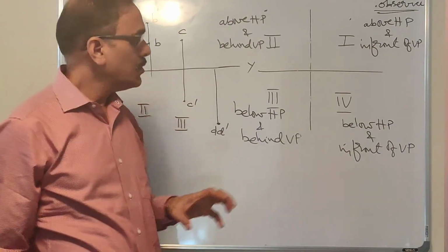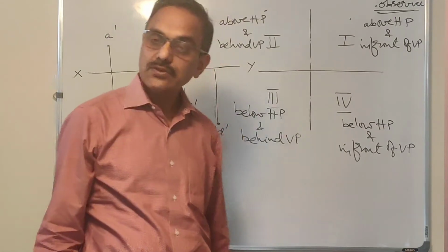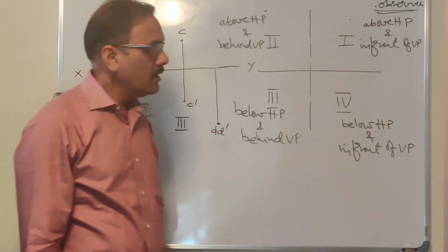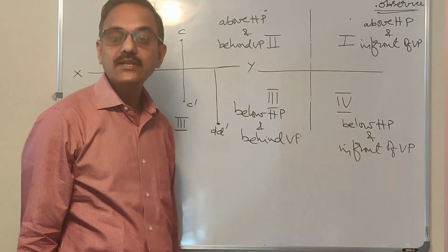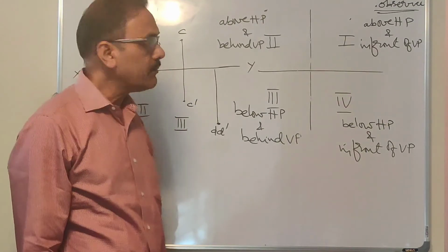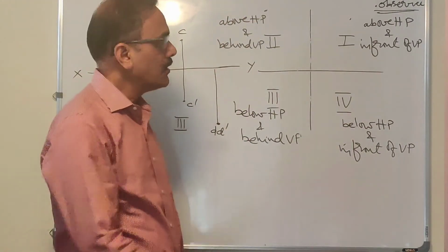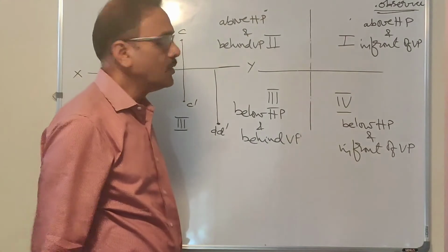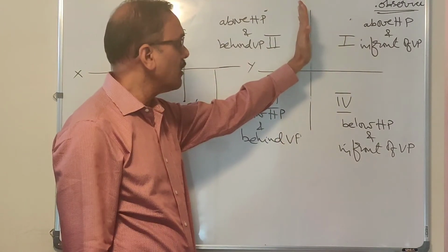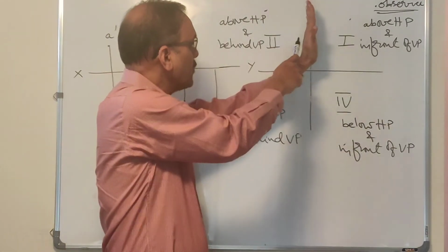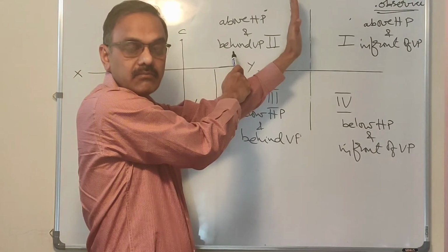Okay. So there is no problem with the first and third angle projections, or first quadrant and third quadrant. The only problem is with the second and fourth quadrants when you consider the relative positions. Let me show it to you. Let us say there is an object in the second quadrant. Now that is the position of the observer. To get the front view, we use the vertical plane. What is the order? Observer, plane of projection and object. The plane of projection is coming in between now.